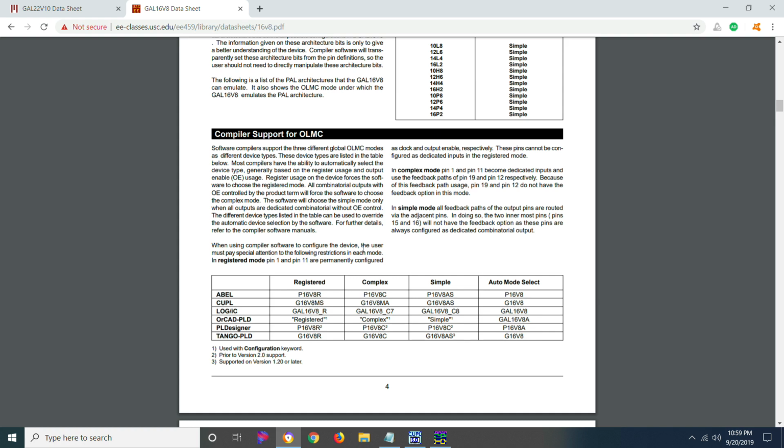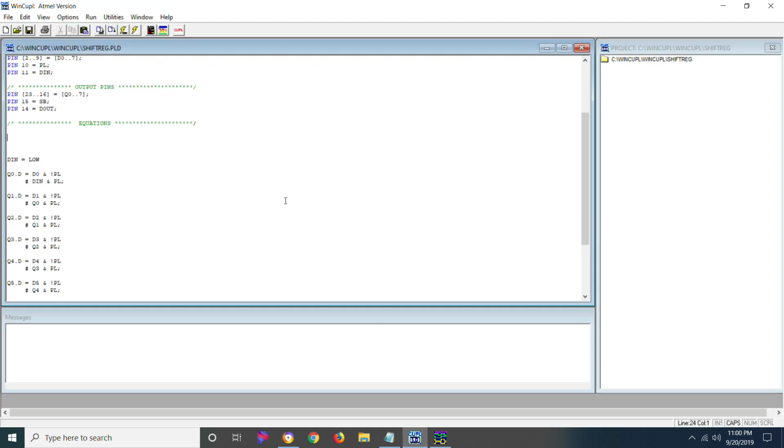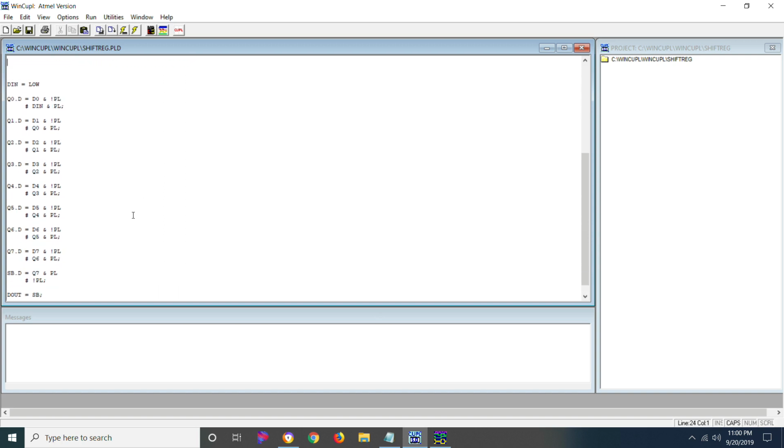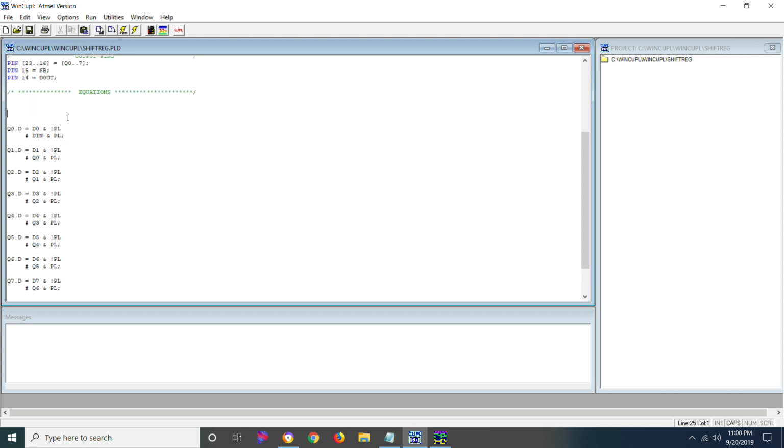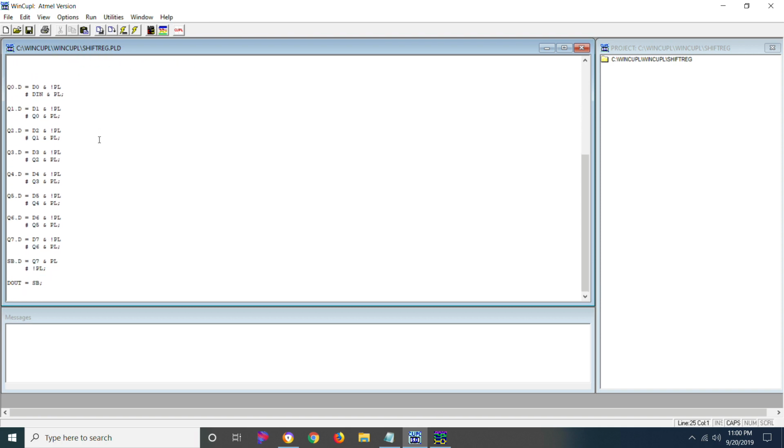Most of the time, if I do need it, it's mostly just to divide a clock cycle in half or something along those lines. So I only need 1 or 2 pins. I just need enough to make it work. But this is something that we will have to take into consideration with this. So what we would have to do in order to make this work is all of these outputs here, we have to set the asynchronous reset and the synchronous preset.